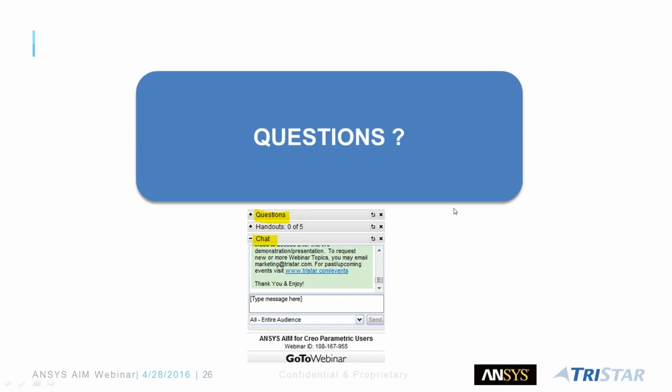How do ANSYS AIM contact elements compare to bonded joints in Creo? Great question. In Creo with Simulate, when you have two surfaces touching each other, it assumes they're bonded, and as you know, we use the P-mesh. However, ANSYS is more of an H-element solver, so when you get into nonlinear analysis, it has better mesh control.